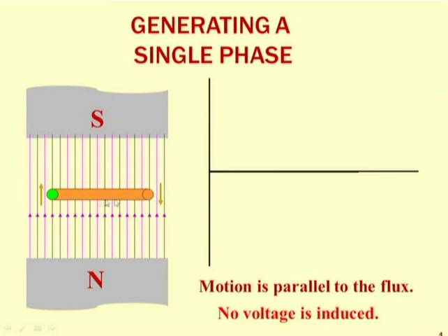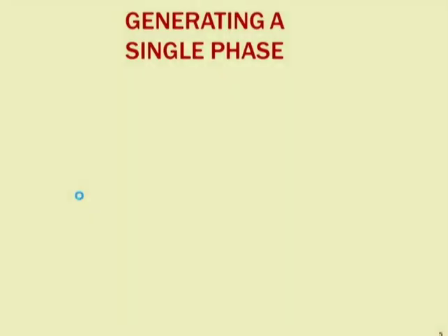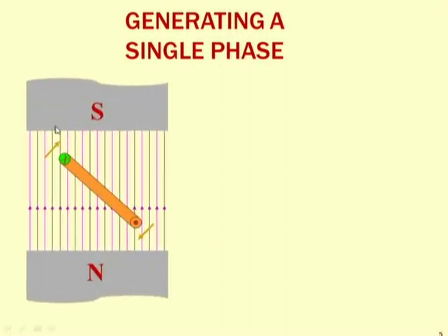As there is no EMF, no current, even though the path is closed, EMF is 0, current is equal to 0. But in this case you can say that now the EMF will be induced. Why will EMF be induced? Because the conductor is moving with some relative motion. As the conductor is present, magnetic field is present, and relative motion is there, some EMF will be induced in the conductor, and the conductor is a coil which is a closed path, say.